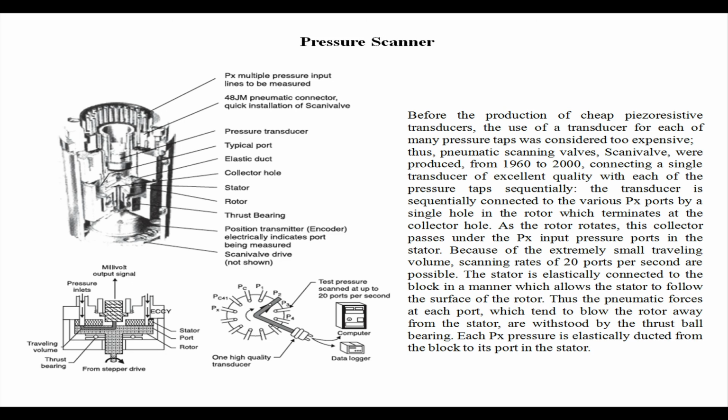But nevertheless, operationally, if the pressure transducer broke down, then the balance is lost. It's as good as useless for the time being, because there is only a single sensor sitting inside, so you don't have any redundancy in the system.